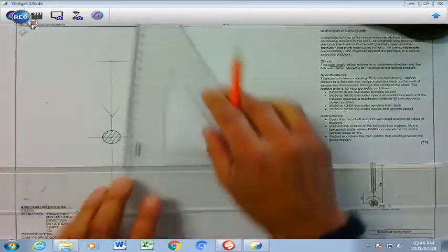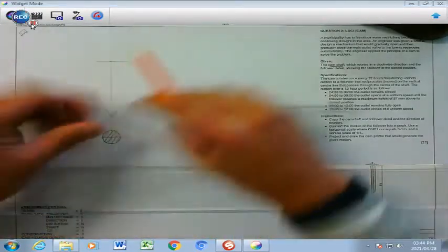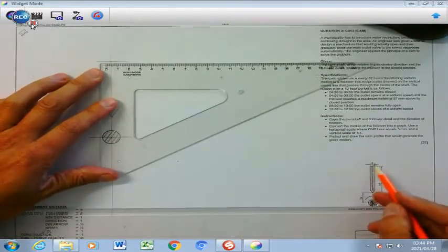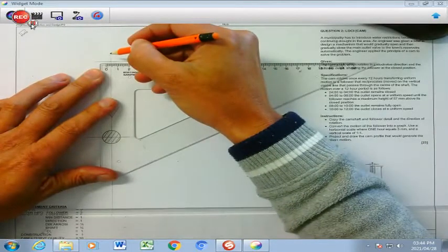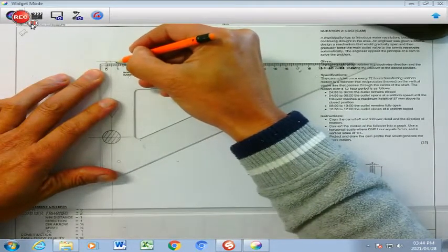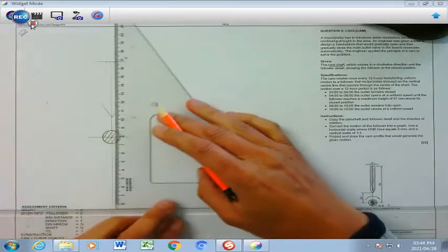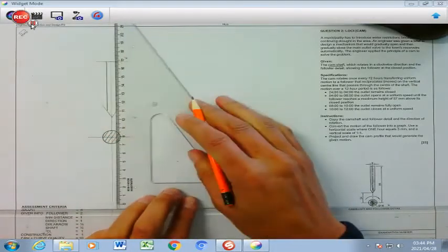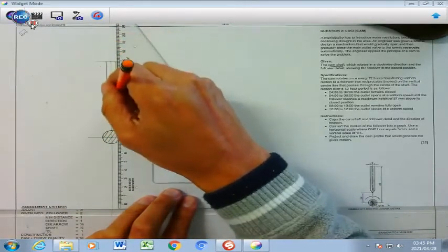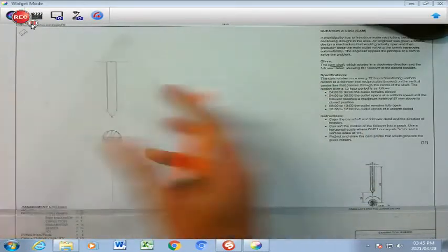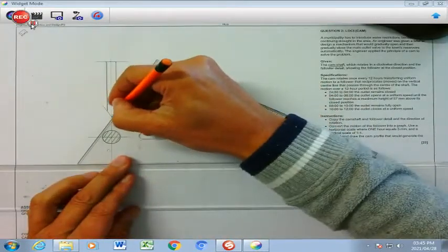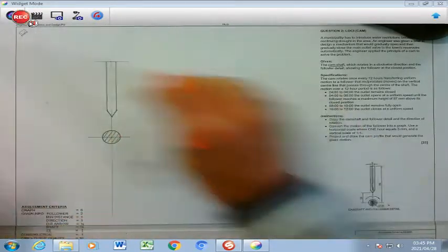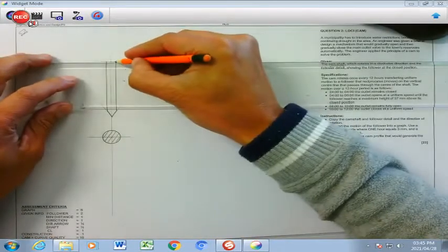This is my center, which I have here, and I'm going to measure 4 off the center because it is 8 millimeters. And to get it perfectly 8 off my center, I'm going to go 4 millimeters and 4 millimeters here, and there I am going to draw my cam follower like that. I will use my 60 degrees just to darken that part there, and my 60 degrees to darken that part over there, and of course my top as well. Here we go.